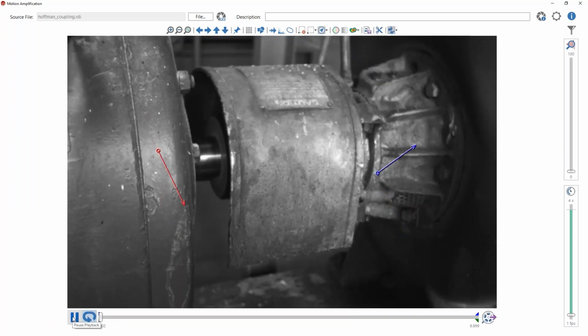So I'm going to bring this over to a coupling where you can show sort of phase, right? If we were to play back this amplification video, you would see the motion go up and down, up on the right side while the left-hand side's going down, right? So they're out of phase, 180 degrees out of phase. And so in traditional vibration, we represent that in different ways.